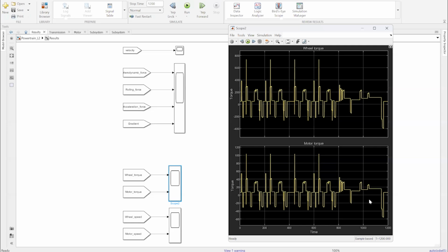If you want to go for continuous torque requirement, you can put some histogram graphs from the results. We can see which value is continuously repeated, so that we can consider it as the continuous torque requirement. And let's say you want to define the acceleration of your vehicle, because usually when you want to develop a vehicle and sell, you need to mention that at this many seconds you will be able to reach this speed.